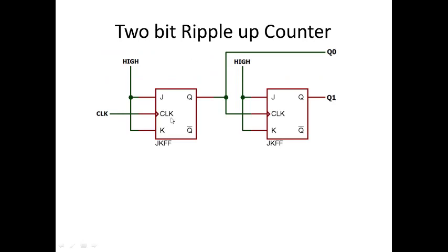So, now this is your A flip flop and B flip flop. Assume that A and B, and usually this is your LSB bit and MSB bit. It's an up counter. So, you have 00, 01, 10, 11. Your transition of states will be like this. It has to be like that. So, your output is QA and QB, or since it is taken as Q0, I can take it as Q0 and Q1.